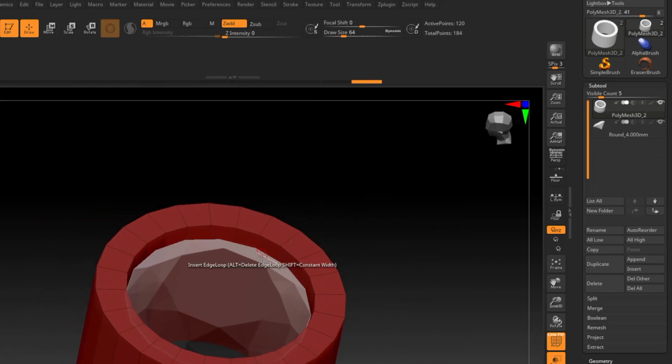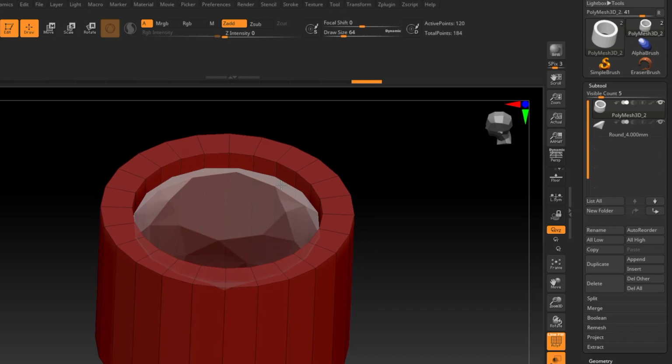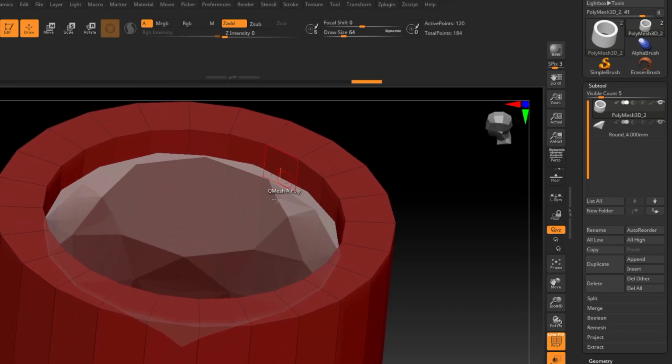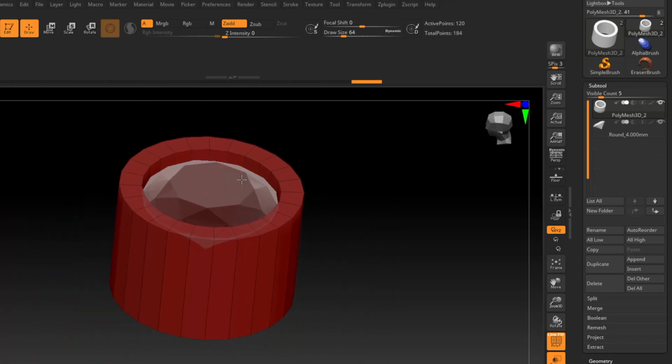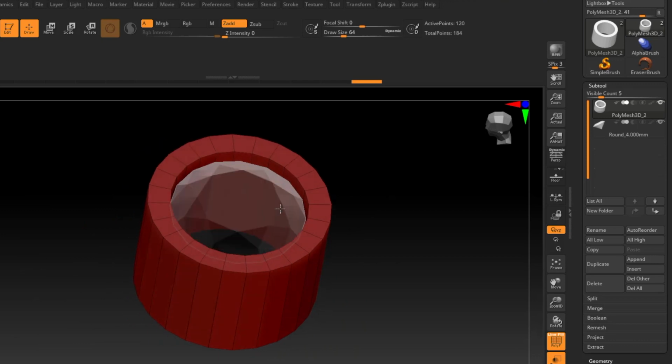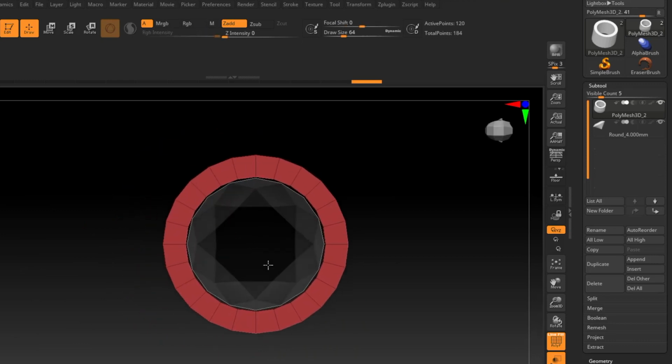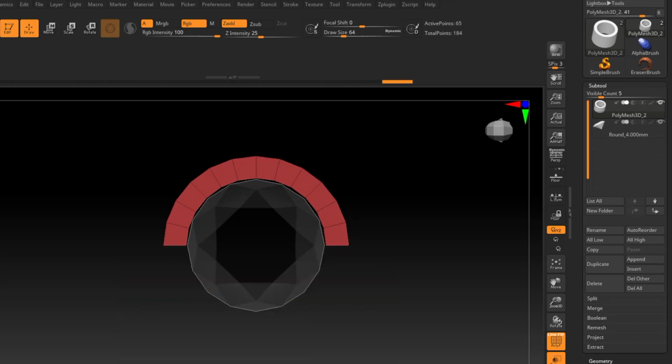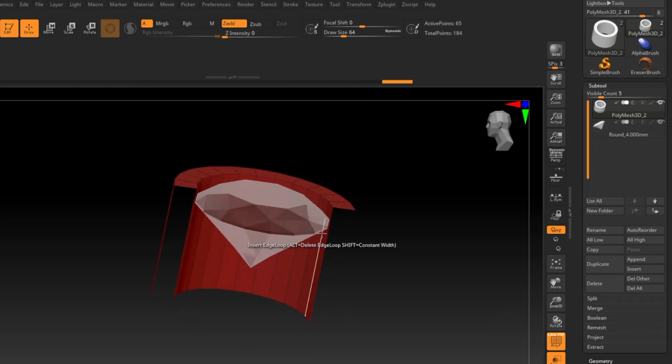We're actually going to check this just to make sure that we have the proper depth. It's a little tricky to see where it's landing, but we can always adjust it later if necessary. So I'm going to go into my top view and hold Shift to snap into that position. And off to the side, I'm going to press and hold Control, Shift, and Alt all at once, and then click and drag this box out. And that will hide that section of the bezel.